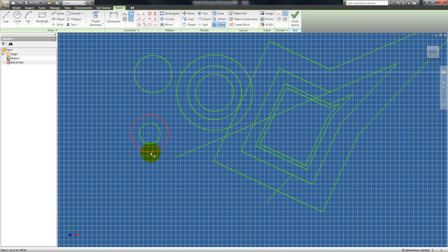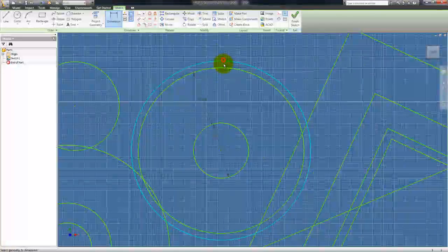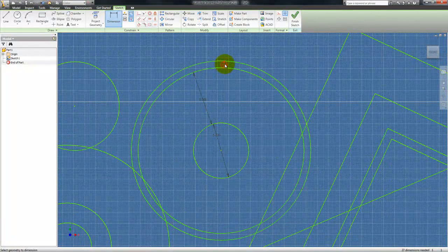Now in AutoCAD, you would click it and you enter an offset distance. So if we want to offset it a meter or a foot, we can offset it that far. But here I showed you how to do this before. First we draw and then we constrain. So now if we want to set our offset distance, let's say we want this to be 5, and then this distance here to be 5 as well. We just go through like that, just like I showed you, adding dimensions to constrain things, and this can be 5 as well.